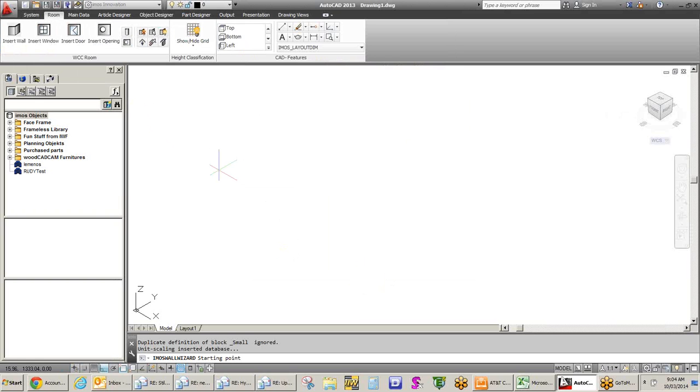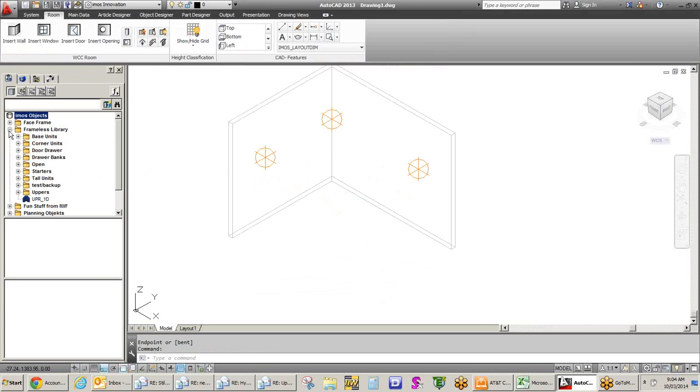And so from the point of clicking that, I would be able to type in distances that I might want. For example, I'll type in that I want to be at 120 inches, and it will continue the wall command as many times as you want to move it. In this case, I'll say 144, and I'll hit enter twice, which will tell it that the command is going to be over.